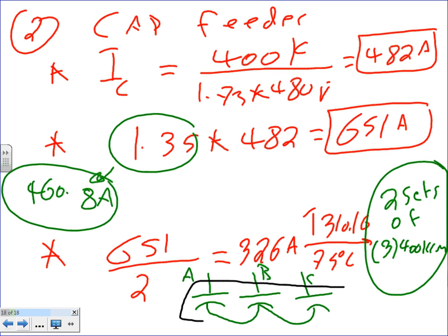Capacitors in a bank. Bring the 3 phases to them, tied from one end. And this could be multiple of them, guys. It's just showing a symbol. Here's your phase A, phase B, and phase C, and we have 2 feeders. We know how to parallel. Any questions, guys, up to this point? By the way, up to number 2, you guys have done that multiple times with me, except the multiplier 1.35.